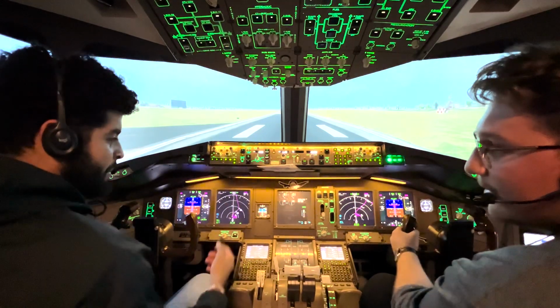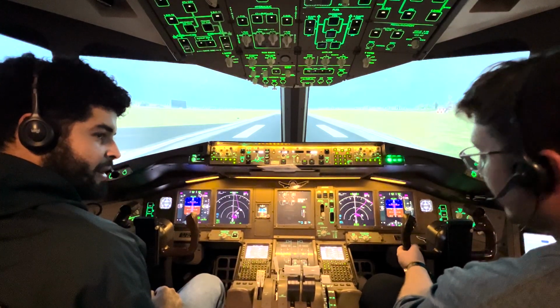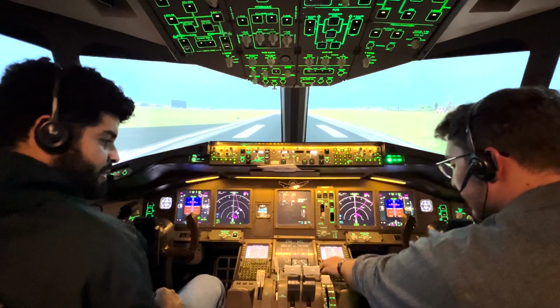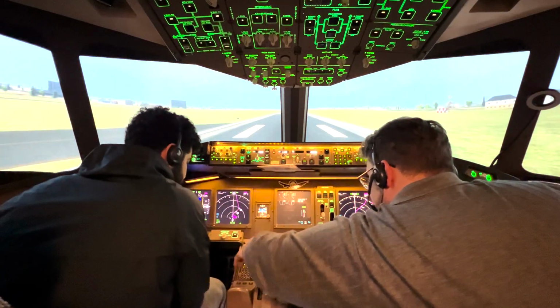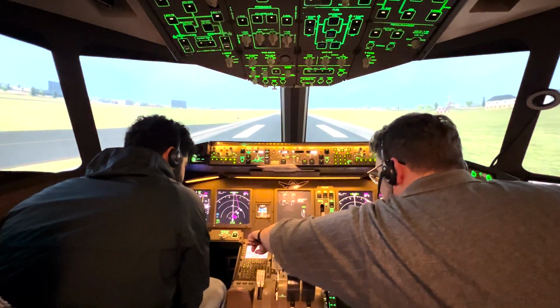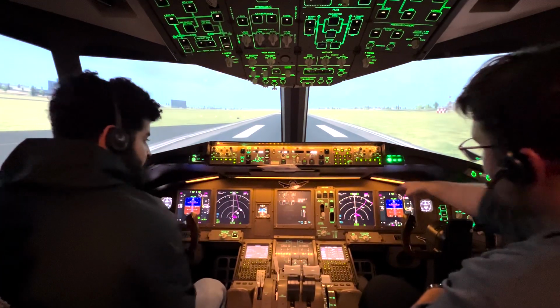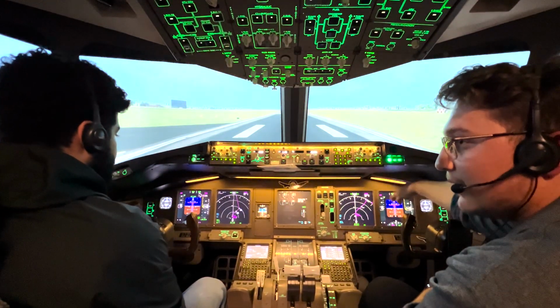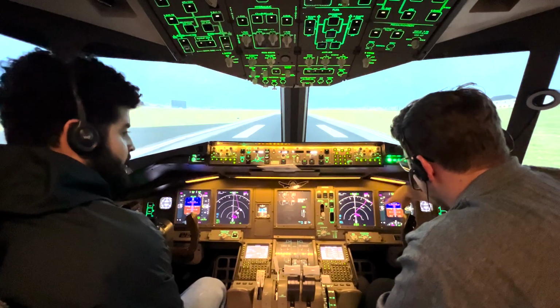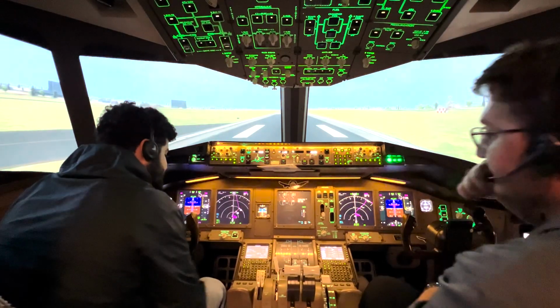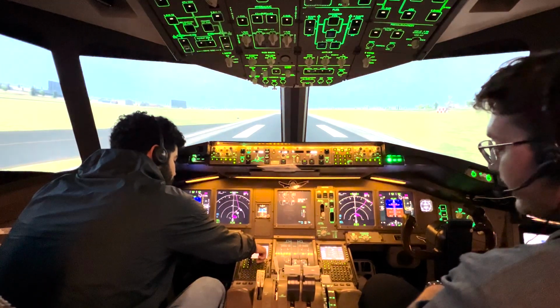At what airspeed am I going to rotate? Our V rotate speed is right here. If you go to route, takeoff, VR speed is 138 knots. You will see the V2 green symbol on your speed indicator here. This is your speed, and that's your altitude. So that's the speed, and it's going to be 138.